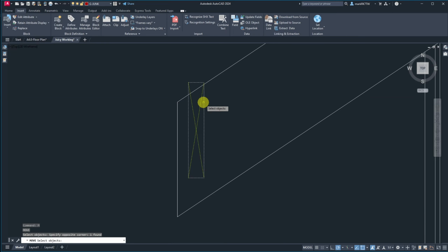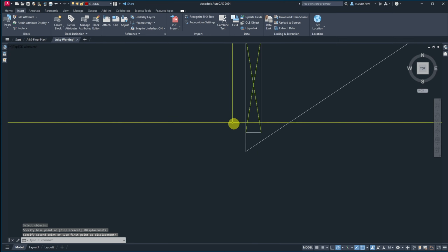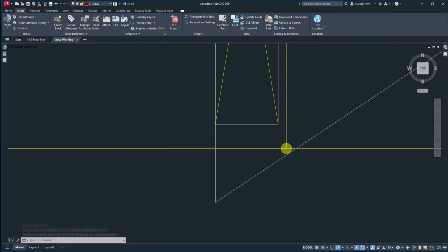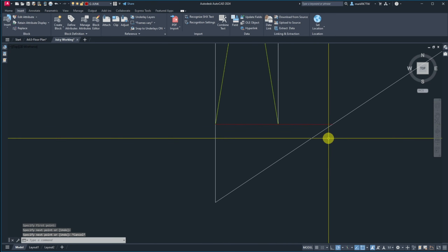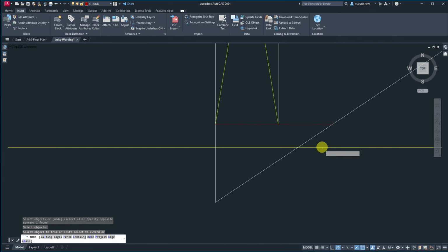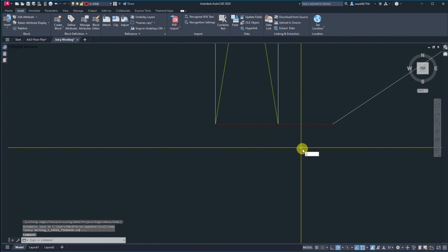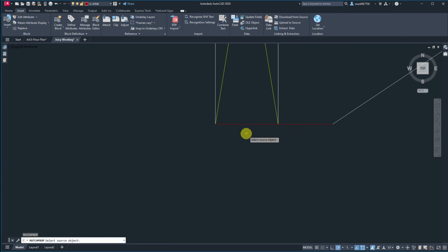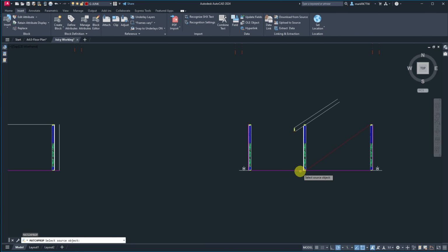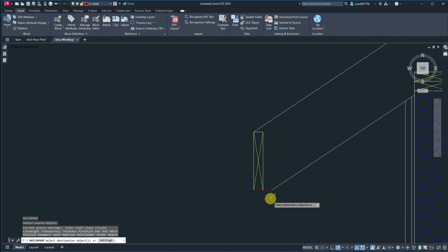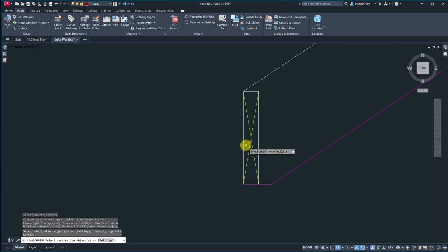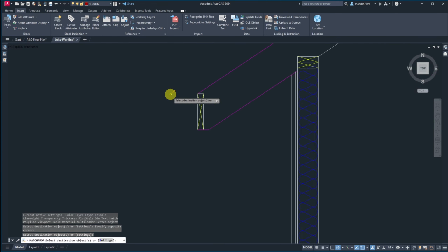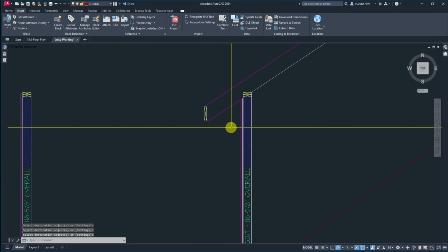So I'm going to move it from here to its end piece, and then this will be cut off. And that's typically what I see. It's not always that way, but so I'll draw straight across. Now I can trim to here, trim both of those, and then just match my properties for, I want this color. If we're doing just the as-built, then it would be here. Well, not that one, but I can't undo that when you're doing match properties.